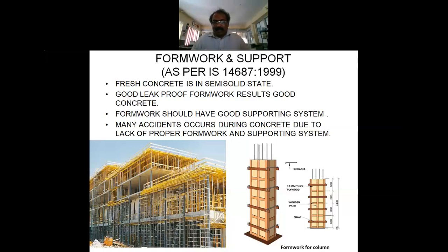So when you, as a site engineer, go to a site, don't simply climb. First go and check the formworks are right and tightened properly. Then you climb, because if anything happens, you will be injured, or even a death is possible on sites.